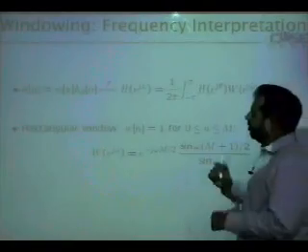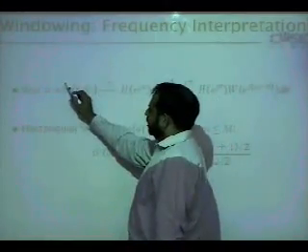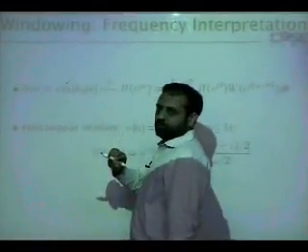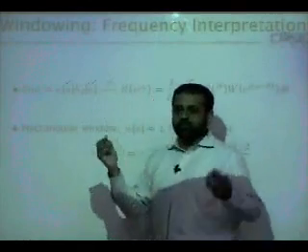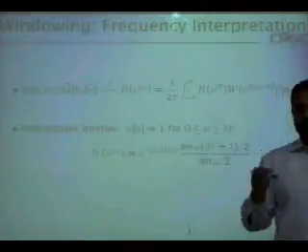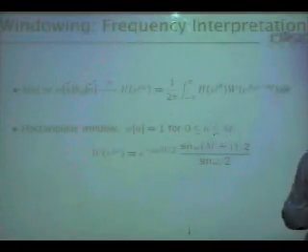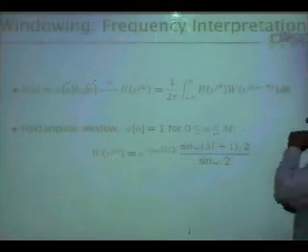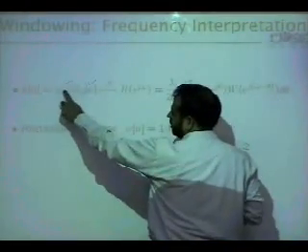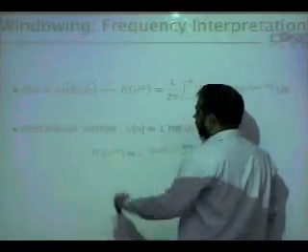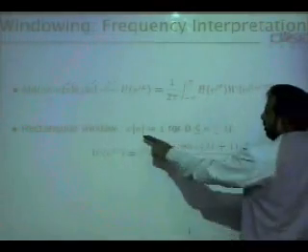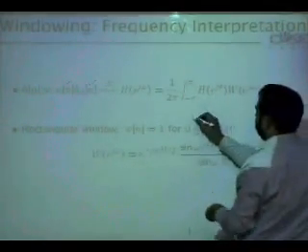Okay, so you need to know the Fourier transform of the window, omega. I already know the Fourier transform of the ideal Hd of n. It is a square pulse in frequency domain. But I need to know the frequency response of this. So the frequency response of a rectangular window, we call this a rectangular window, all one.